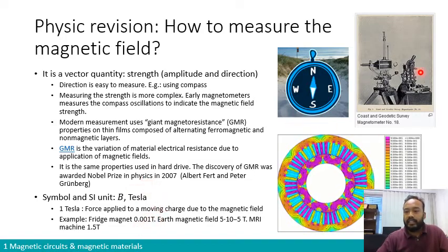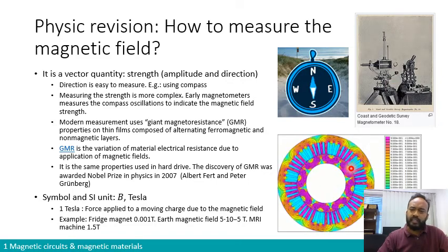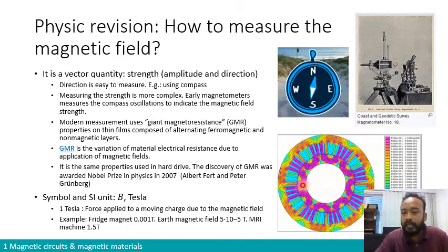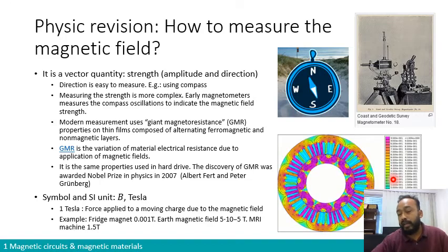So this is the figure of an old magnetometer, right? And underneath here is a finite element analysis of an electrical machine, an electric motor. This is a synchronous motor with internal permanent magnets. You have the color scale over here for the intensity or strength of the magnetic field. Purple describes the highest intensity, and turquoise or blue describes a lower magnetic field, right?